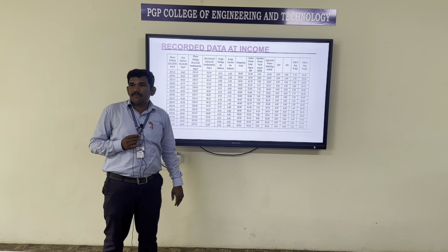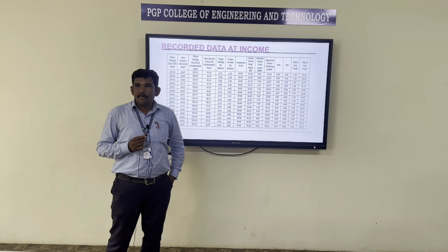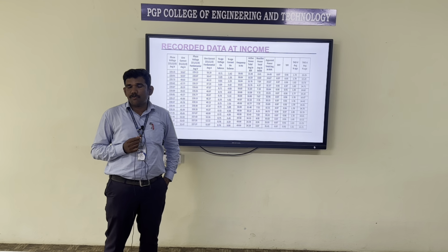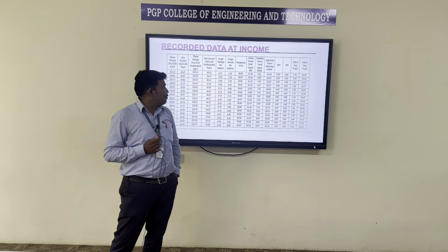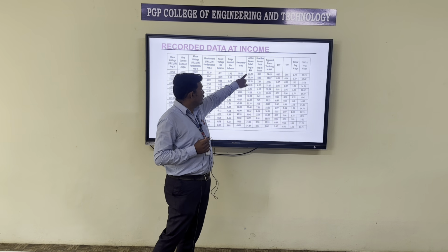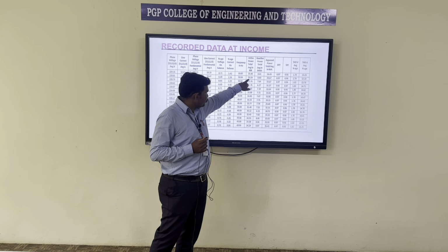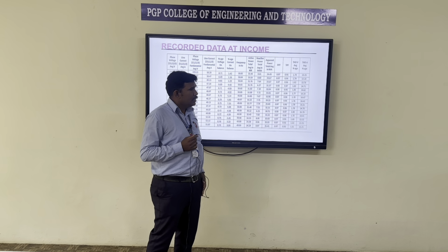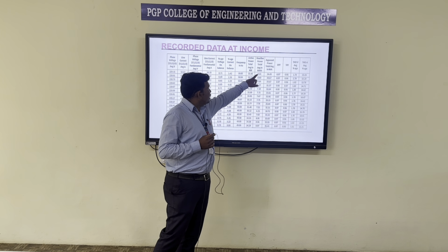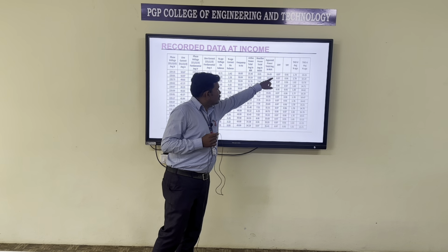In India we are maintaining the frequency of 50 Hertz, but in real time it is maintained at 49.5 to 50.5 Hertz. So these are the powers: the real power is VI cos theta, whereas VI sin theta is the reactive power. So these are the power factors.